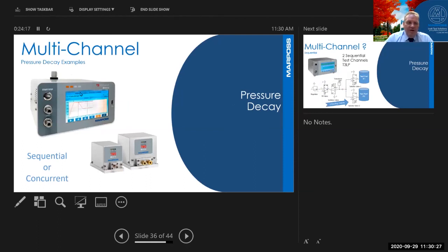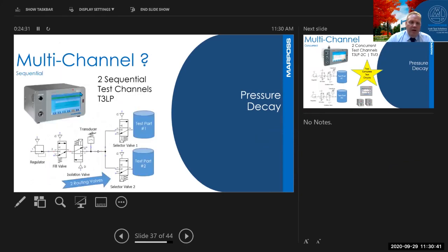Multi-channel testing, this starts getting a little different and a little strange on terminology. Multi-channel to different people means different things. So a lot of times when we're talking multi-channel, do we mean sequential or do we mean concurrent? What do I mean by that? Would we consider this multi-channel? What this is, it's a pressure regulator, the fill and the isolation valve, the transducer, but we add 2 routing valves. This is really 2 sequential test channels.